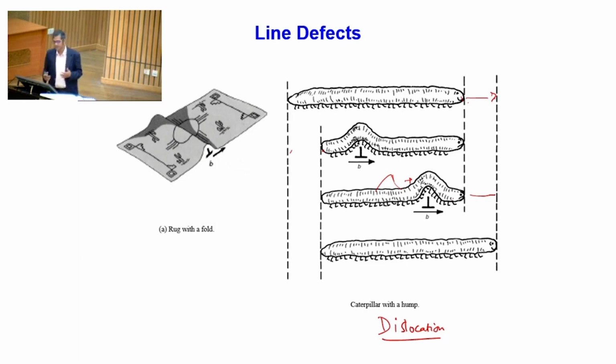How is it done? Well, that is very simple. A caterpillar moves in small parts. It does not move the whole body like us. When we walk, we walk with the whole body, right? But a caterpillar moves only a small part of it, and then that movement is transmitted from one part of the body to the other part. So, the whole process leads to a finite displacement. As you can see, from here to there, the finite displacement is possible simply by making a fold in its body. That is how a dislocation actually moves in a material, and that is obvious because this motion requires much lower energy than breaking the bonds altogether in the material.